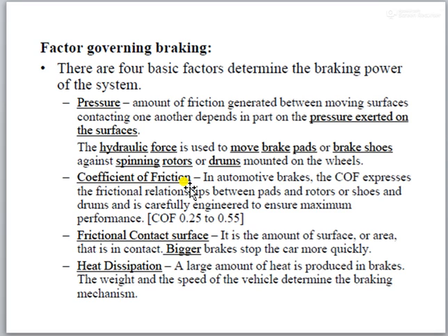Now sometimes it also happens that whenever the pressure and braking efficiency increase, the wheel can lock. A wheel locking problem will be there, that means your road wheels get locked and your vehicle starts skidding on the road surface. So that is nothing but the problem of wheel lock. Okay, so to overcome that, the ABS is there. That is a new thing which came into the brake system.